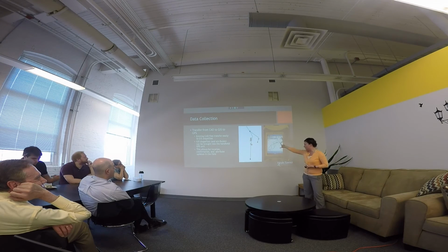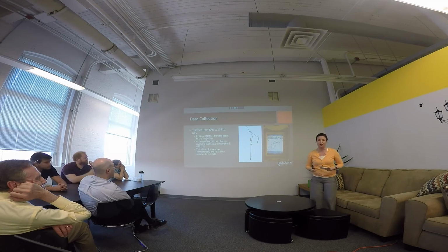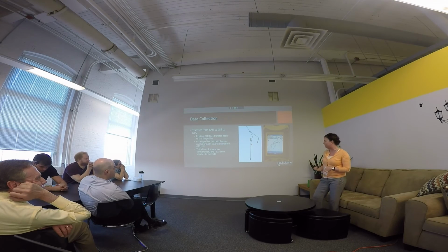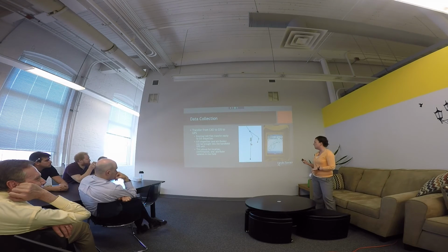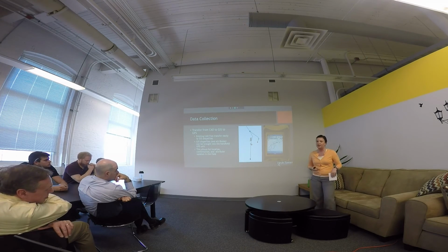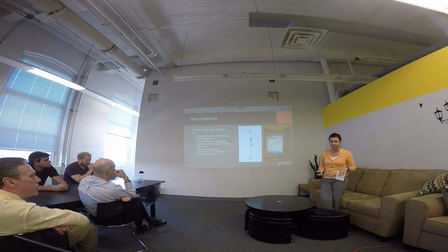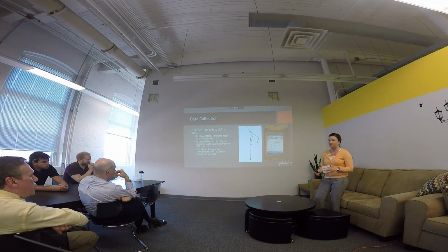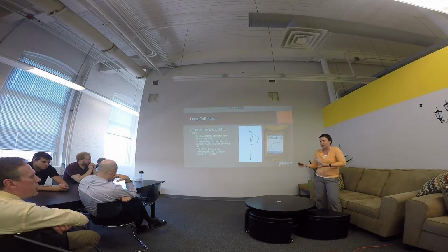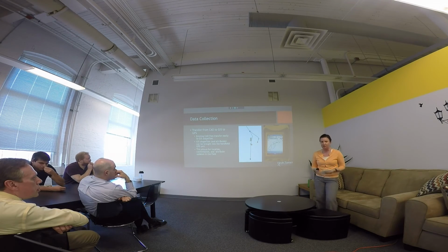So that's what the water system looked like before I went out and used the GPS. I was able to transfer basically the layers from CAD to GIS to the GPS. The advantage of that is that all the attributes go with it. Once it's transferred to GIS, it becomes a data file rather than a layer. Layers are basically dumb lines in CAD, but once they're transferred to GIS, they mean something, and you can use that in run calculations.